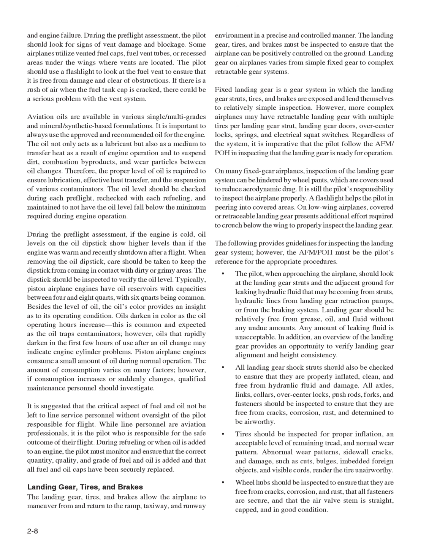Fixed landing gear is a gear system in which the landing gear struts, tires, and brakes are exposed and lend themselves to relatively simple inspection. However, more complex airplanes may have retractable landing gear with multiple tires per landing gear strut, landing gear doors, over-center locks, springs, and electrical squat switches. Regardless of the system, it is imperative that the pilot follow the AFM/POH in inspecting that the landing gear is ready for operation.